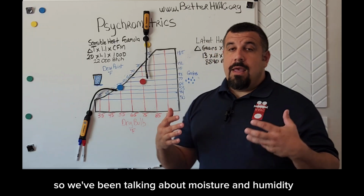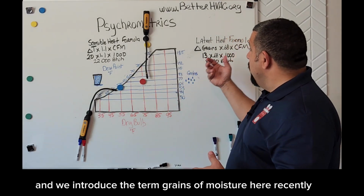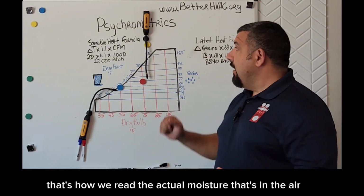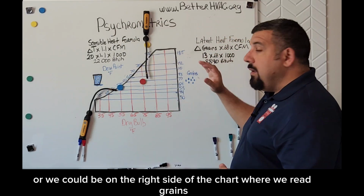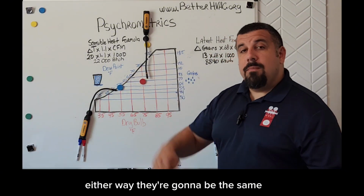So we've been talking about moisture and humidity, and we introduced the term grains of moisture here recently. That's how we read the actual moisture that's in the air. It's part of the absolute humidity. We could be on the left side of the chart where we read dew point, or we could be on the right side of the chart where we read grains.